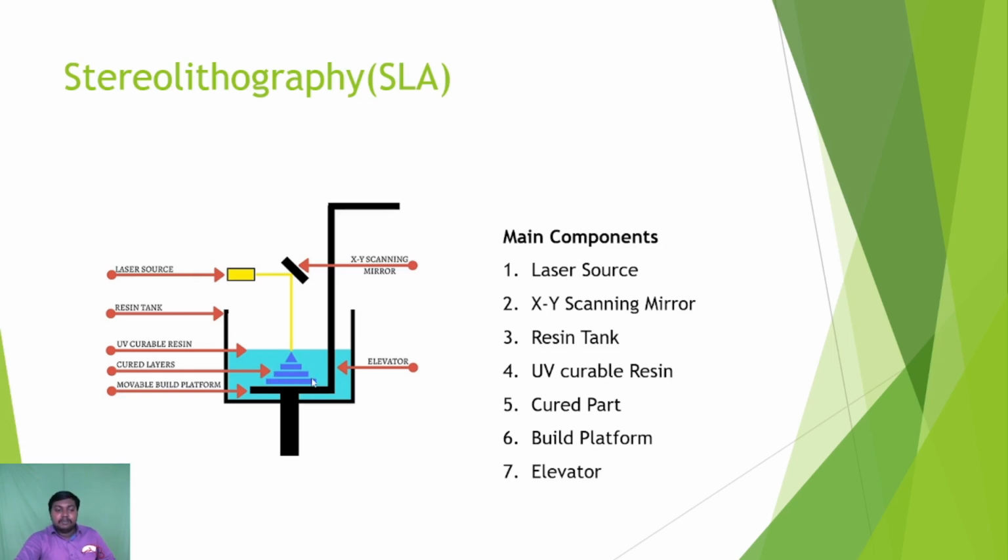After that, the elevator system moves below 0.1 mm, or 150 micron to 100 micron, in the Z direction, and the next layer forms by using the laser as a heat source.